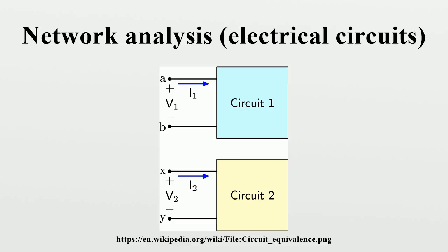For the three passive components found in electrical networks, the transfer functions are as follows. For a network to which only steady-state signals are applied, S is replaced with j omega, and the more familiar values from AC network theory result. Finally, for a network to which only steady DC is applied, S is replaced with 0 and DC network theory applies. Two-port network transfer functions, in general, in control theory are given the symbol H.